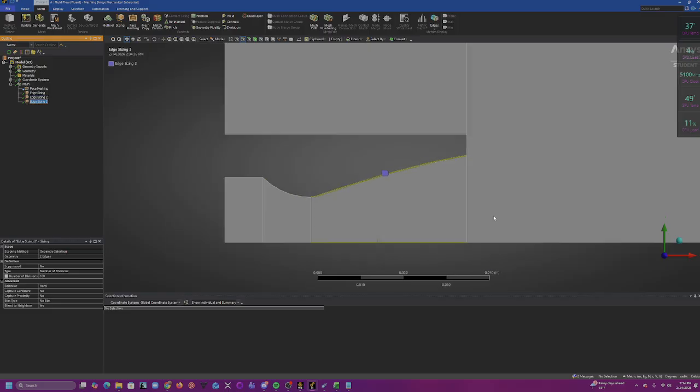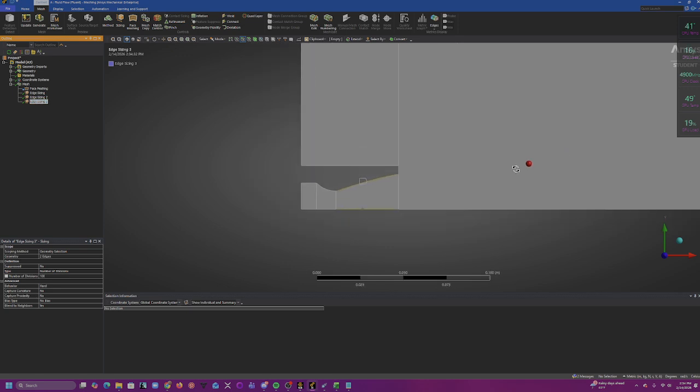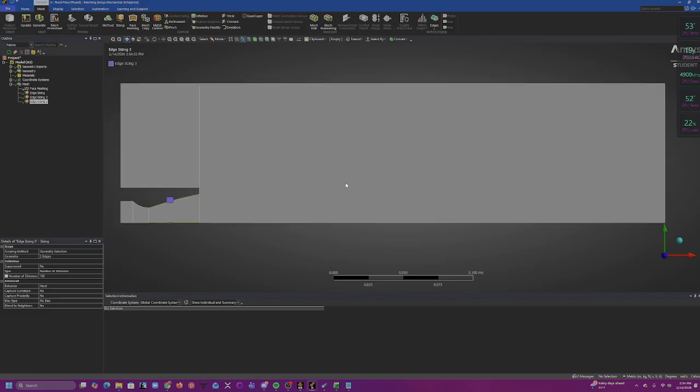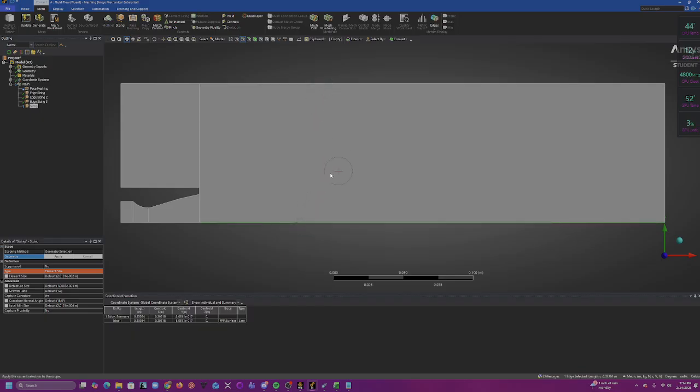All right, cool. So once we got our three edge sizings, we're going to be moving on to this section right here. This section we can put, let's see, we can add another sizing. It's going to be from this horizontal line to this horizontal line. So you can just click and drag. Again, make sure you have edge selection selected, right? And then we can click apply.